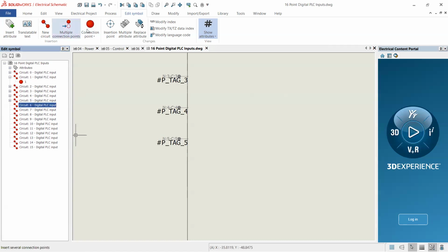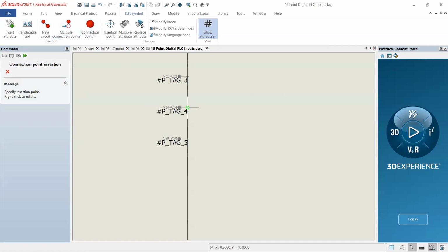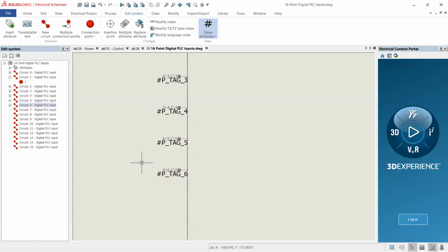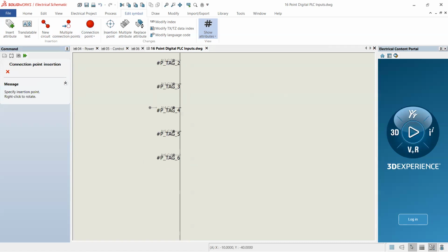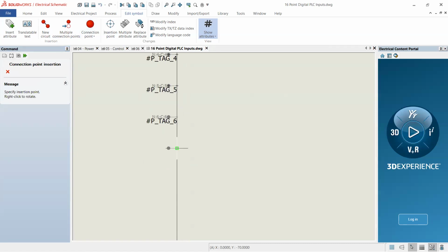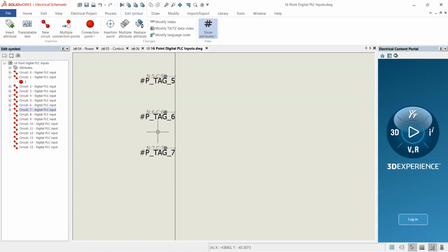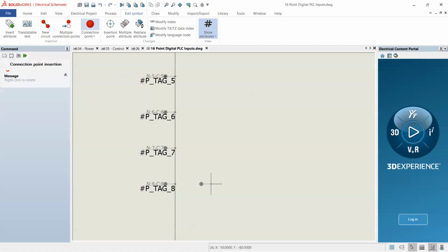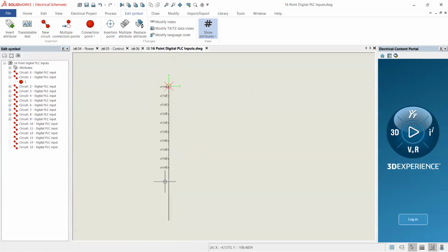Now we'd also need to watch out, because each one of these line segments also has a snap point in the middle, and it's going to be hard to hit with the way my snap settings are. That'll show up as a triangle under your cursor. I can't even zoom in, the box doesn't get any bigger. Right now it's a square. If you're in the middle of a line, it'll be a triangle, so just make sure you're at the right point. There are reasons you might want to be in the middle, that's fine, but whoops, undo. See, I spoke too soon and snapped to the wrong point.